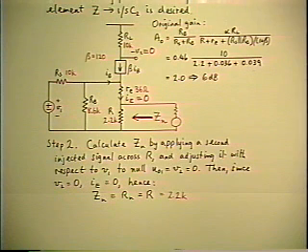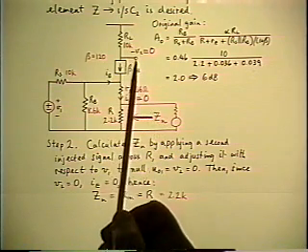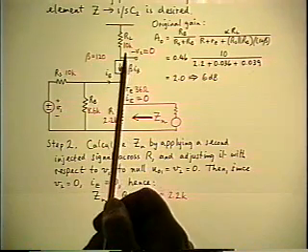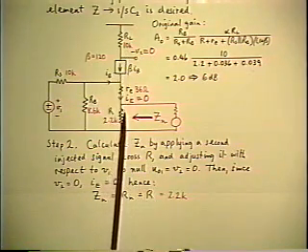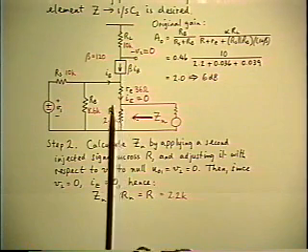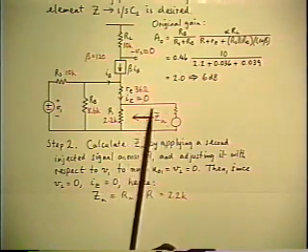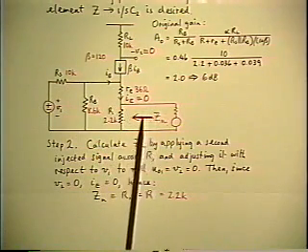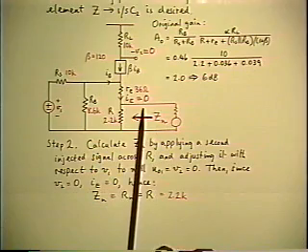So I describe now what the sequence of argument is that enables you to do that. The way you do it is you start with the null and you propagate the consequence of the null towards the second source. The purpose in doing that is you want to know what happens to the current going in from the second source. That's what enables you to calculate the Zn.